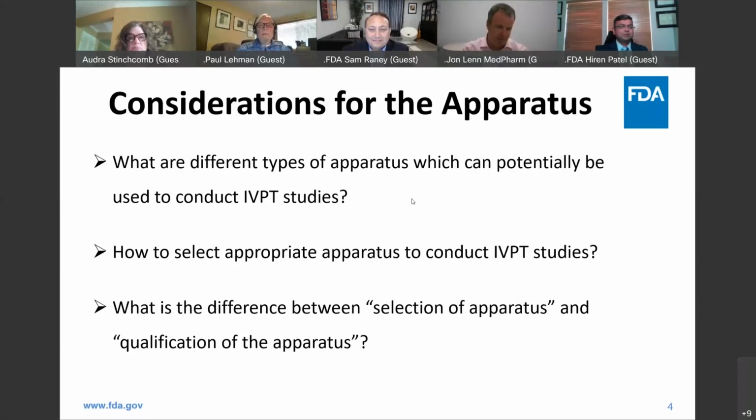I mean, I'll speak up here. We typically do those qualifications annually because they can be quite labor intensive, especially if it's the static vertical diffusion cells where you have to measure things and then weigh them out. And if you have hundreds, that can be time consuming. It's also unlikely that those parameters are going to change very much given the fact that they're glass, so you don't expect big changes. I will say that for instance in the flow-through cells, tubing, because those are moving parts, there can be some stretching involved. Those tend to get qualified on a different schedule.